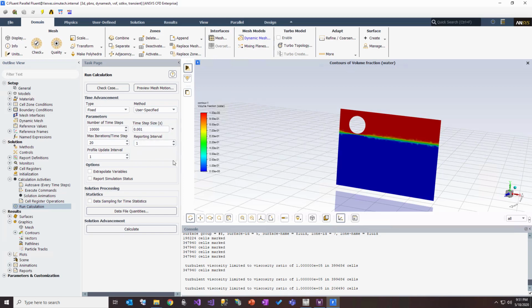As you can see, it's small, but it's important to have a good time step for your application, since we have dynamic meshing and we also have multi-phase flow, and the impact of the capsule with the surface and the meshing and all the dynamics that are happening during that have to be captured. So you may even end up using a smaller time step to avoid any kind of issues. When everything seems to be fine here, we can start the calculations.